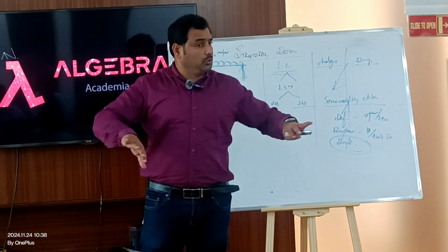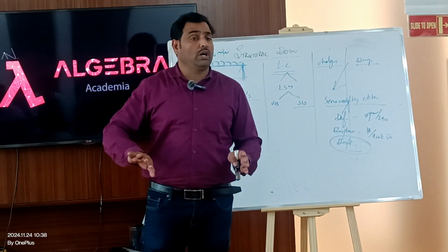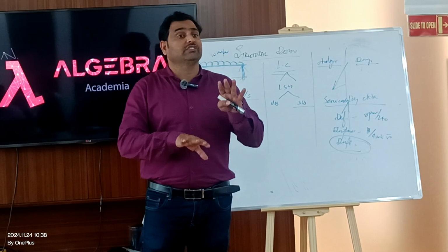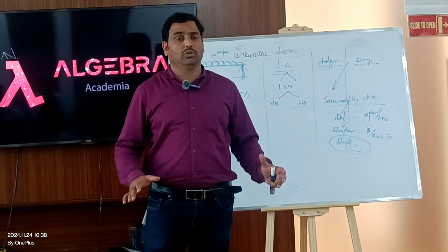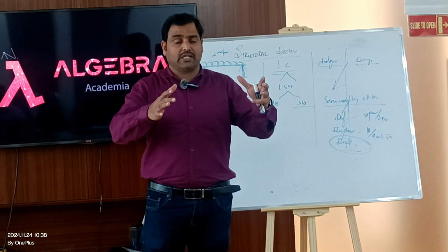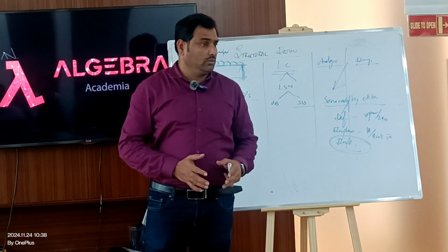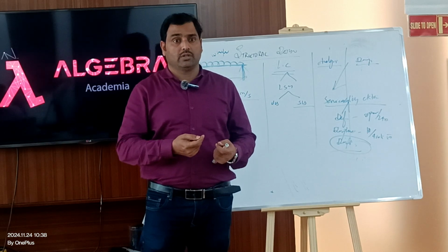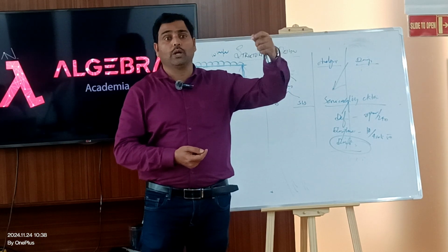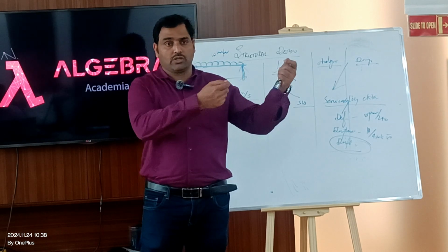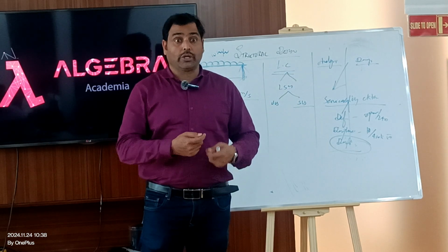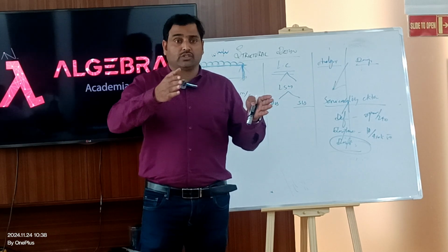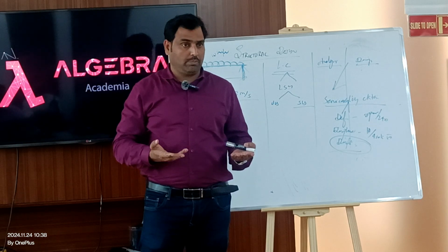When you have an irregular footprint, maybe you have a large cantilever. Maybe you have a difference in stiffnesses. Below you may have bigger columns, and when going up, the columns suddenly stop and you need to take new columns as planted columns. These are all irregularities in the stiffnesses, irregularities in the masses. Maybe on the 10th floor you have a huge load due to MEP, the MEP floor. So irregularity in the masses, irregularity in the footprint itself. Maybe the tower itself goes step by step, with respect to architecture.